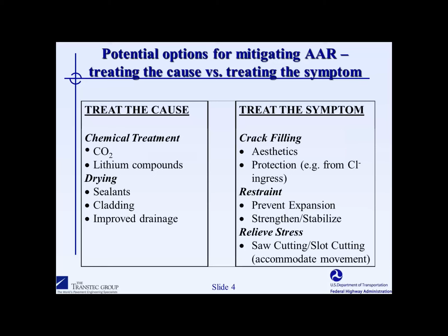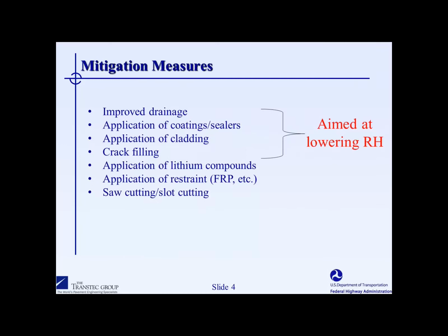Other things we can do and that will be described will be to restrain the concrete. In other words, to make the concrete that's already expanding essentially go into compression by confining it, typically externally. And this does not stop ASR. The gel is still there. It still tries to expand, but we're going to physically try to stop it from expanding. And lastly, I'll talk at the end of the presentation about some techniques where we try to relieve the stresses that form in an ASR-affected structure, and I'll give a couple of case studies on those as well.